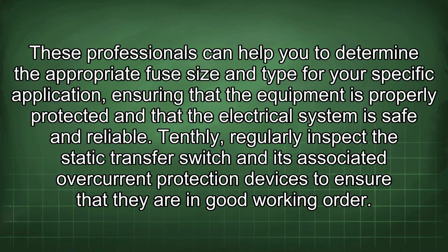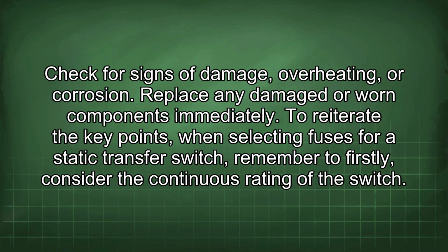Tenthly, regularly inspect the static transfer switch and its associated overcurrent protection devices to ensure that they are in good working order. Check for signs of damage, overheating, or corrosion. Replace any damaged or worn components immediately.